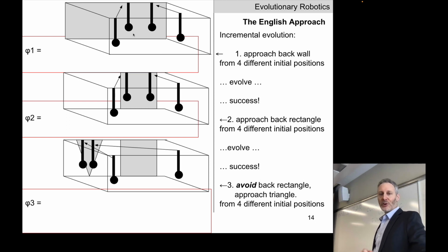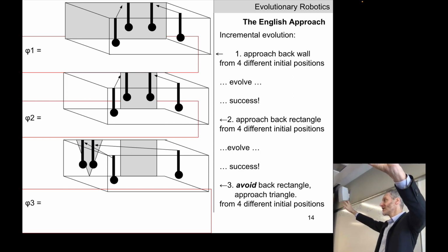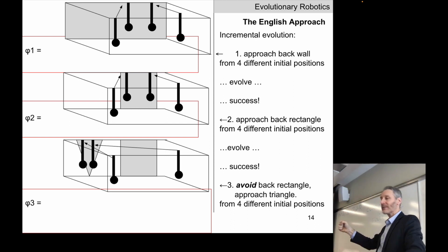Okay. First task is they're going to actually evaluate every neural network controller 4 times inside the robot. So they've got one vector with all the synaptic weights plus the 9 numbers encoding the fovea. They're going to download that onto the robot, drive the turret so that it's at some particular XY position under the table, and then let the neural network controller control the robot. Press enter, it reverses what it just did. Then they send the turret to some other random XY coordinate, and with the same neural network controller, they let it drive the robot again, a 3rd time, a 4th time.